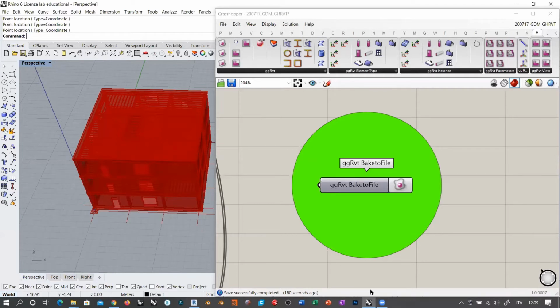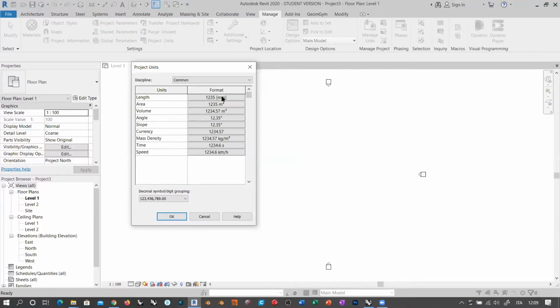Okay, so if I import this inside a Revit project set to work in millimeters, I will have a building of basically 1.5 centimeters, which is going to be somewhere in this area, extremely small. And so this is something very common. It happens often with Revit users that try to import things without paying attention to the units.